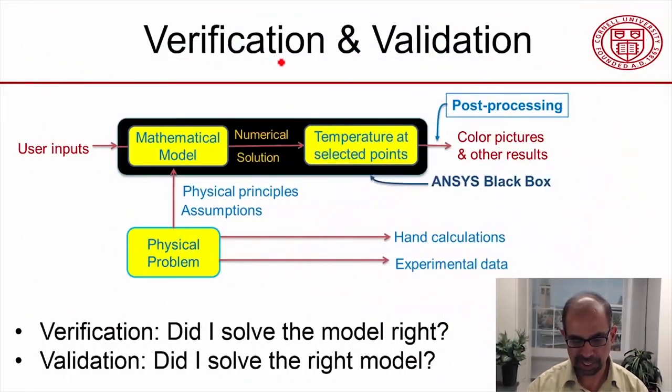That brings us to the end of the conduction module, and in the process we have explored some really fundamental ideas in finite element and how you implement it using ANSYS. Let's do the verification and validation. Verification is looking at whether we solved the mathematical model correctly, whether we input the right mathematical model and we solved it correctly.